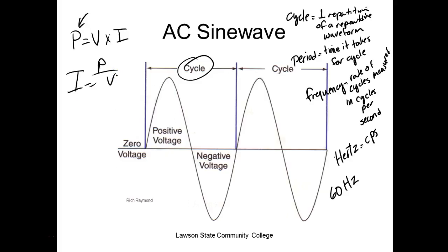All I did was move that formula around. So if I'm trying to give you a certain amount of power, the higher I can make that voltage to deliver that power, what goes down? Current. And the amount of voltage drop I get in my wire, V, is equal to I times R.